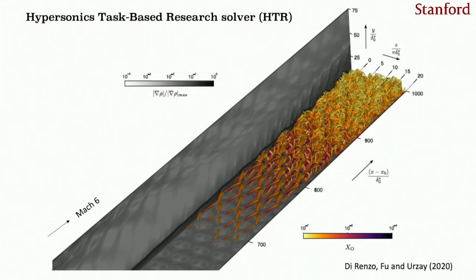The effect of air dissociation is double. First, air dissociation is always an endothermic effect in the net, so it's going to drain energy from the flow. And secondly, in order to treat dissociation, invariably one also needs to incorporate the effects of temperature on the specific heat, because if the gas is dissociating, of course, the gas is already vibrationally excited.